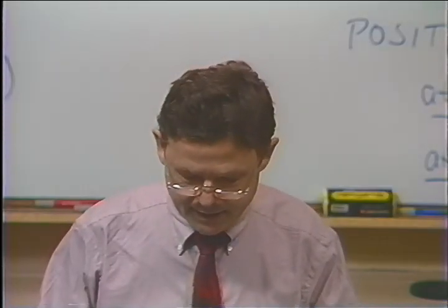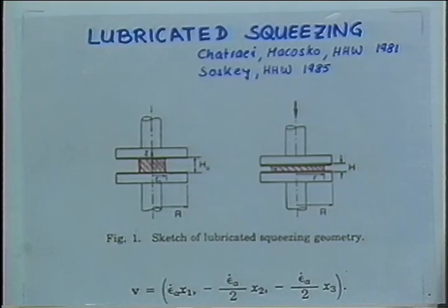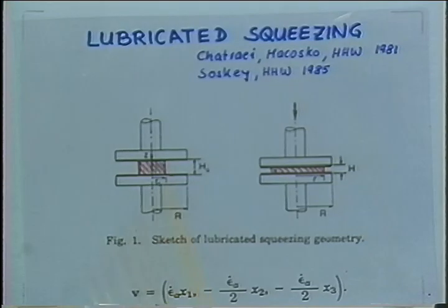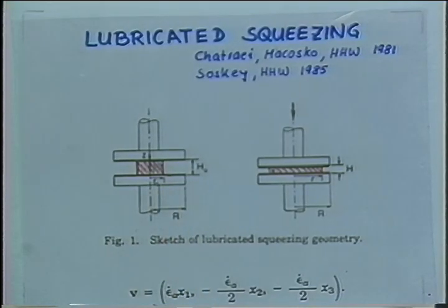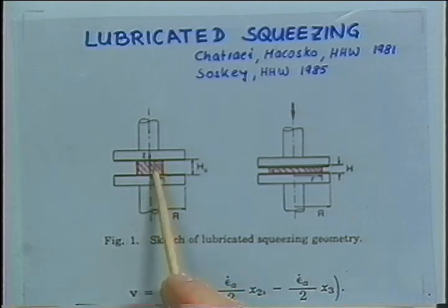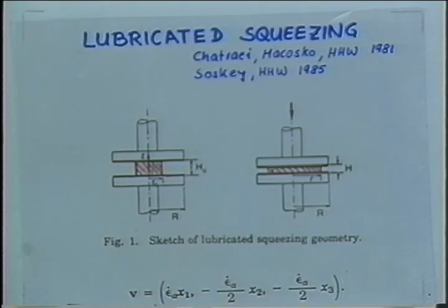in this device. Now, we had some fun also with biaxial extension, and our approach was the following. To produce biaxial extension, we would squish a sample between two approaching plates. This is a sample also maybe 5 millimeters high in the beginning, but the surfaces here are lubricated with a liquid which has a viscosity about 500 to 1,000 times less than the viscosity of the sample.